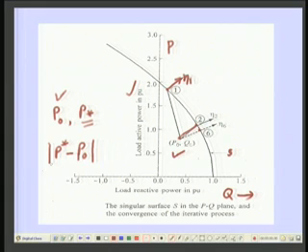Our objective is to find the norm of rho star minus rho naught, and this should be minimum. This process is documented in various papers, on how to find this norm for a multi machine or large system. The purpose of obtaining the shortest distance is to know at what stability margin we are operating, because whenever you are operating a system, you would like to maintain a certain stability margin all the time.